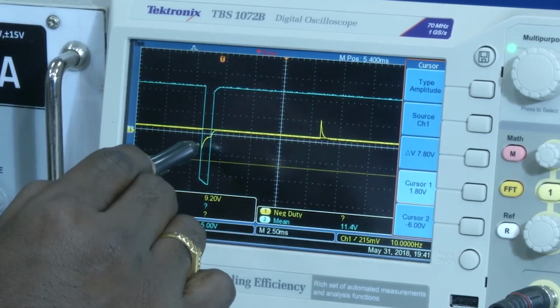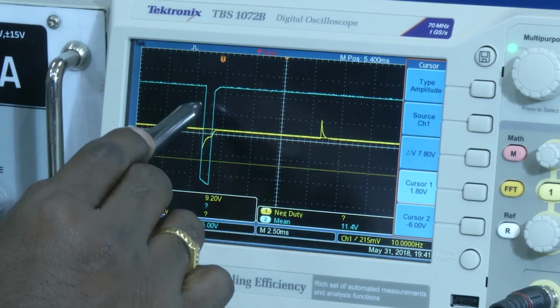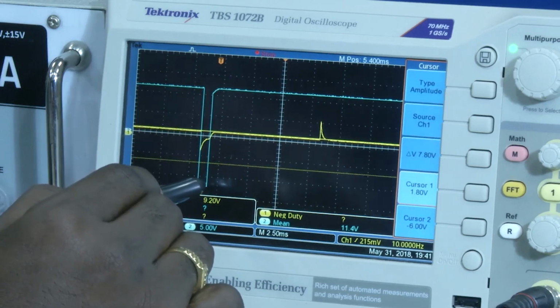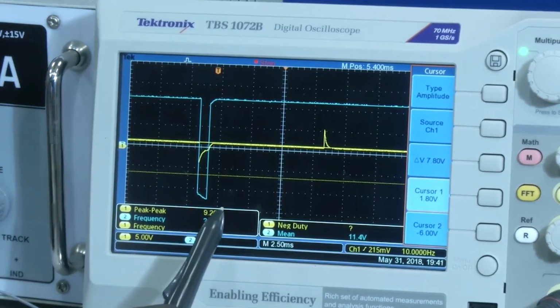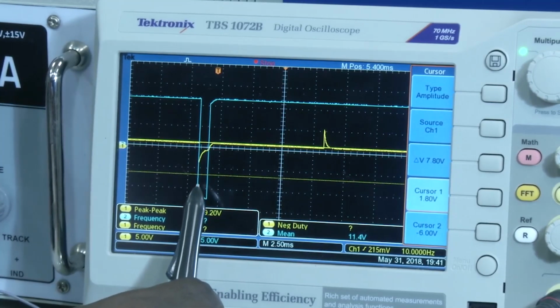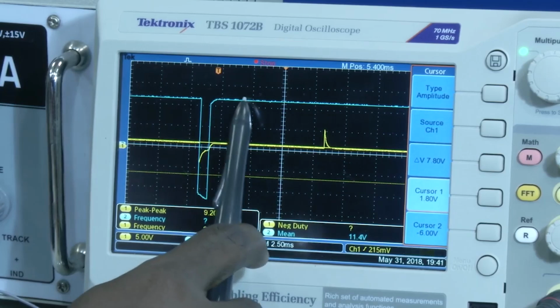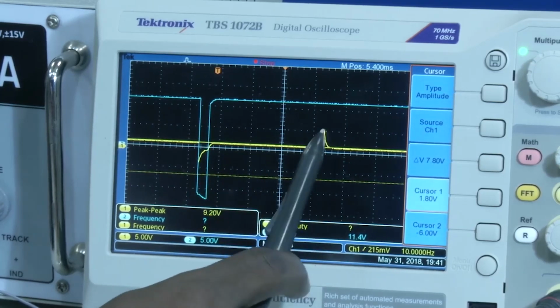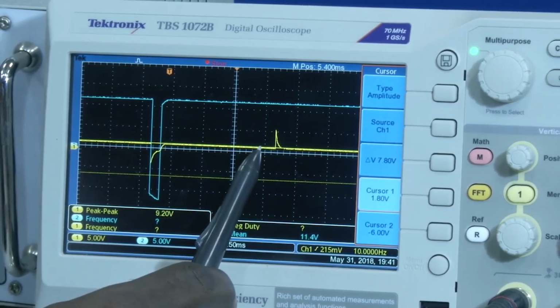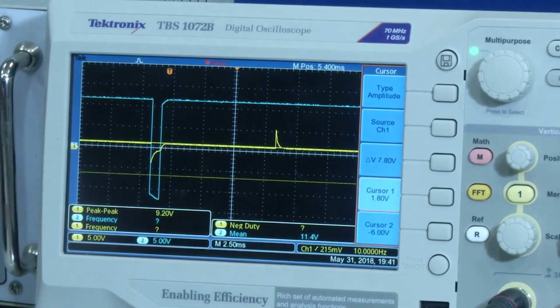starts discharging, right. So, whenever it goes to minus 7.5, then it goes to minus VCC. So, it is going to the minus VCC, and again when the value is greater than 7.5, it is again going back to the plus VCC, and this spike we can see because this is the voltage we are observing before the diode. After the diode, even that we cannot see, right.